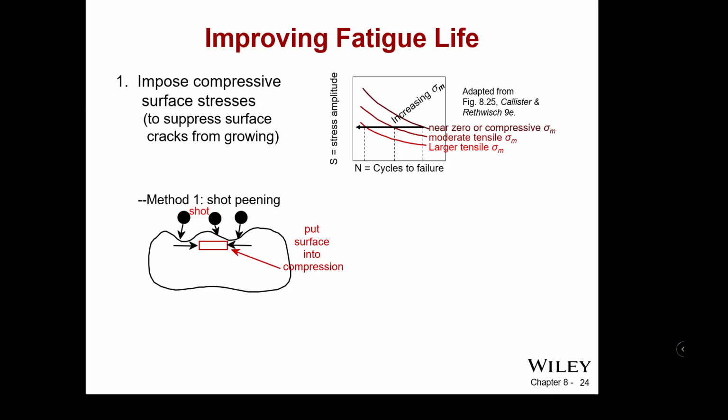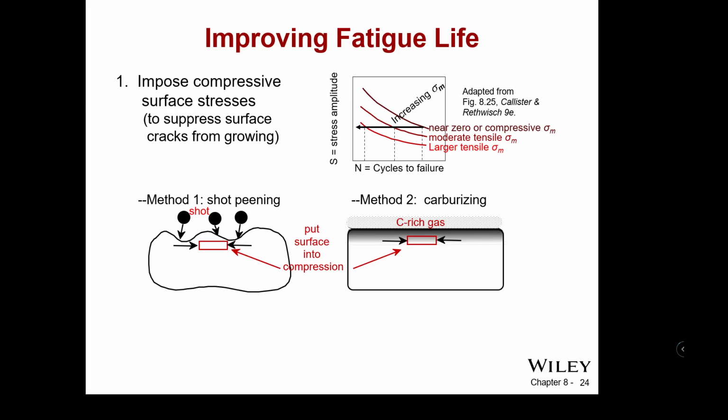So you'll see shot peened chains, for instance, and chain links are much greater in strength than a chain material that hasn't been shot peened, because they literally shoot shot at it in order to make impressions in the surface that compress those grains together. That compression in the surface makes the material much harder, and therefore